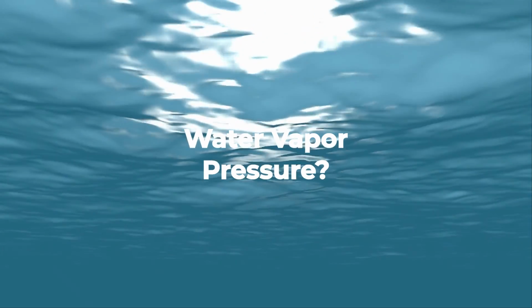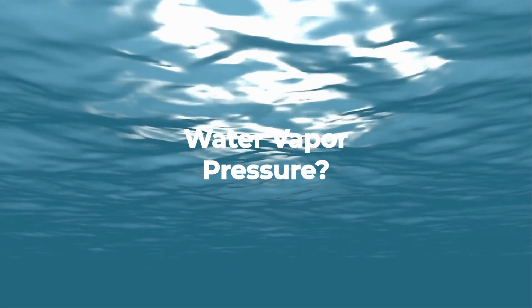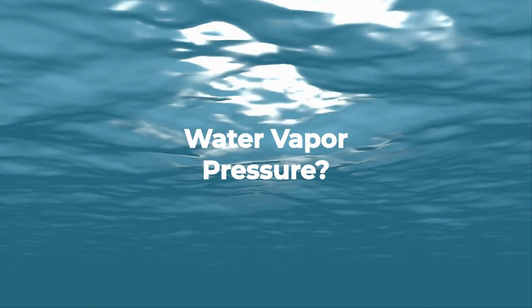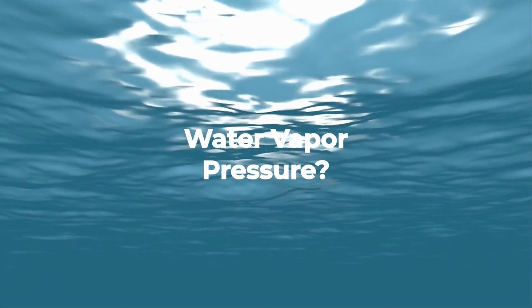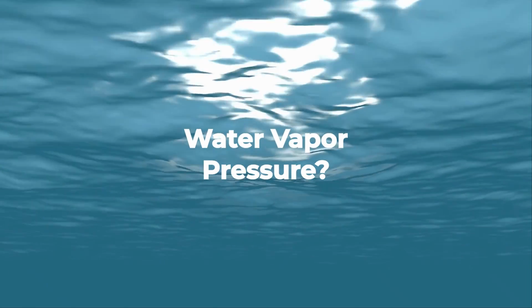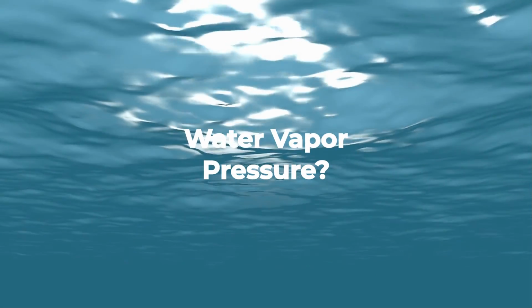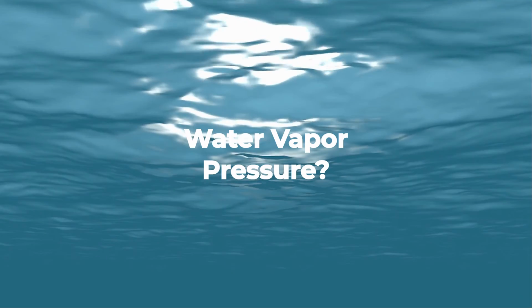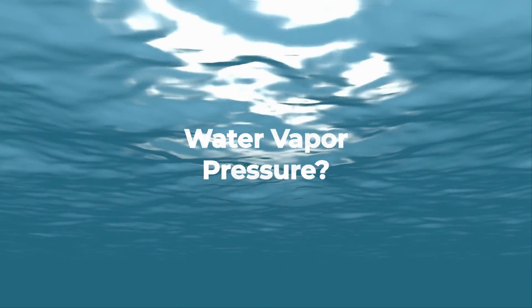That's the point where that liquid is turning into a gas, and that's going to give you very erratic readings. What's even worse is downstream, when that gas turns back to a liquid, that's called cavitation. That's even a bigger problem for you. So yes, knowing the vapor pressure of the liquid is pretty important.